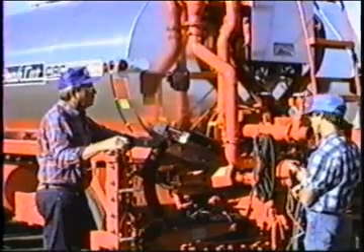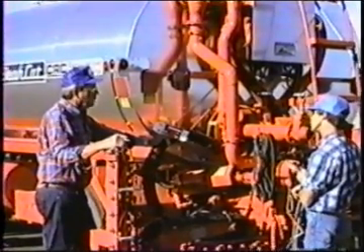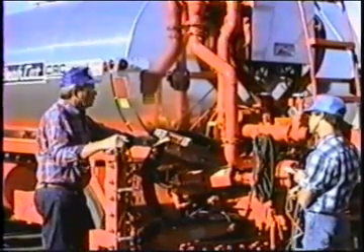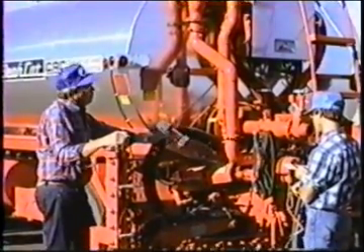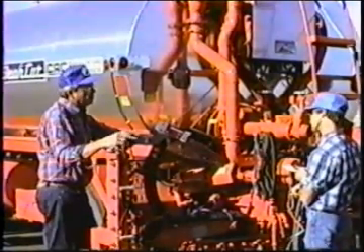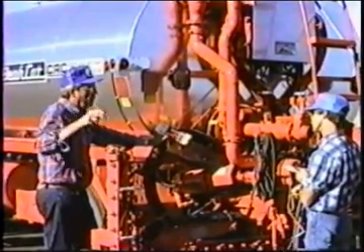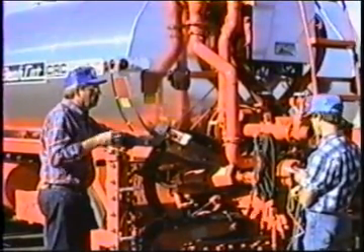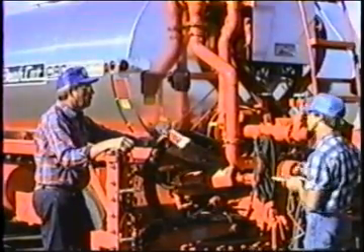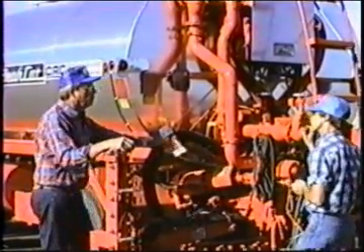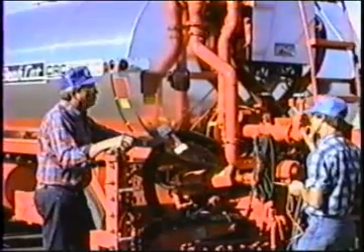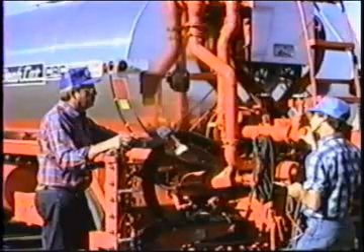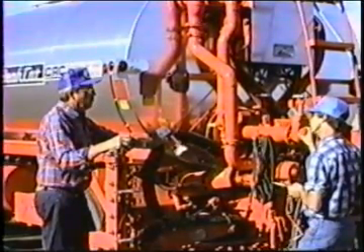Now that's on a non-computerized machine. On the computerized machine, of course, the computer is going to regulate the speed of the pump. We could do it that way on the non-computerized also, but you're just not fast enough to shut off a foot of spray and then reach down and change the speed of the asphalt pump to the right place. You can't keep up with it. So in order to change bar widths with a non-computer truck, we have the relief valve. And we have the bypass valve then, and we use that bypass valve to regulate the pressure when we're changing widths.